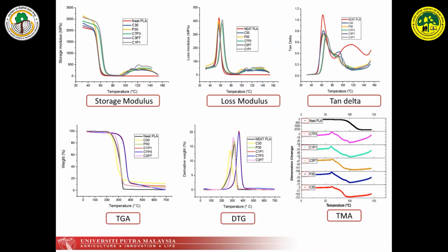Then we did a study called the dynamic mechanical analysis. In there, you can look at the stiffness and properties, how the materials behave with temperature compared to the mechanical. We only studied the mechanical. So we did the storage modulus, loss modulus, and tan delta, and we analyzed that beside the thermal properties, TGA and TMA. TMA is one of the techniques you use to analyze the physical properties of the materials with temperature. Further.